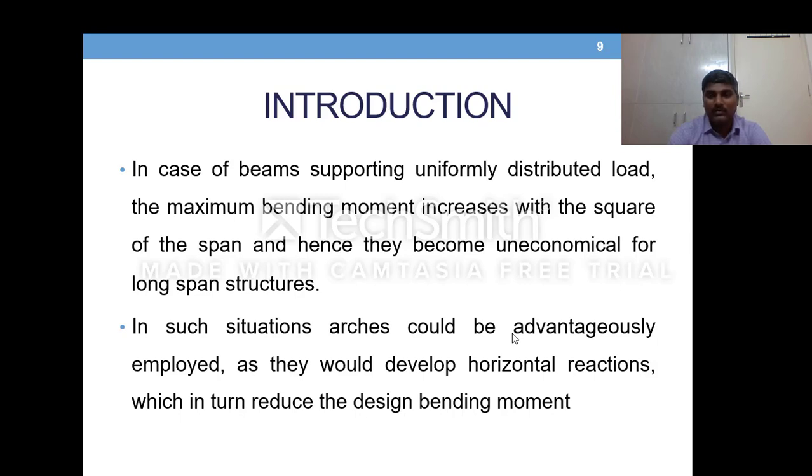When you say beam, we will have vertical reactions at the supports and no horizontal reaction. Whereas when you come to an arch, the ends of the arch are hinged. Hence, we expect horizontal reaction when the gravity loads are applied on the arch. That horizontal reaction will bring down the bending moment developed in the arch.